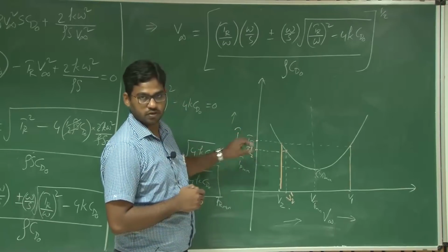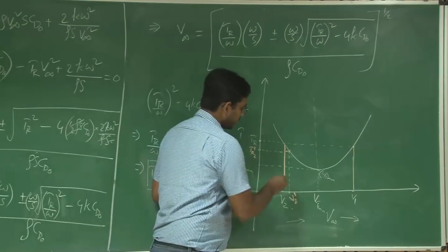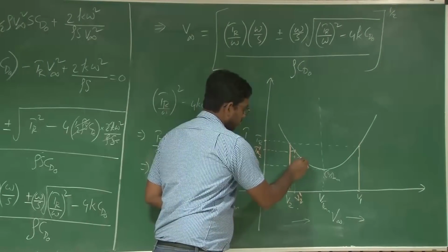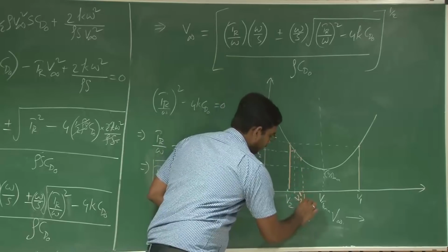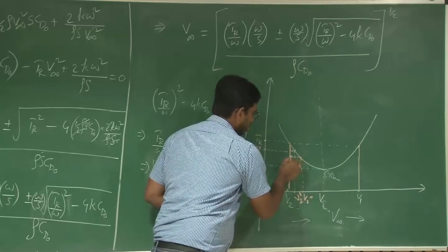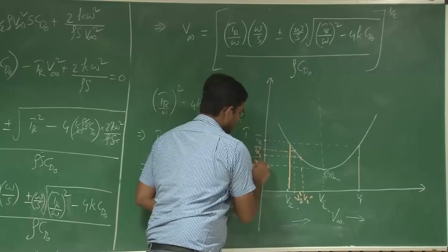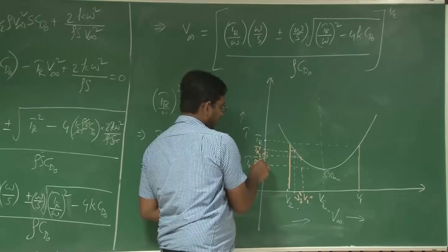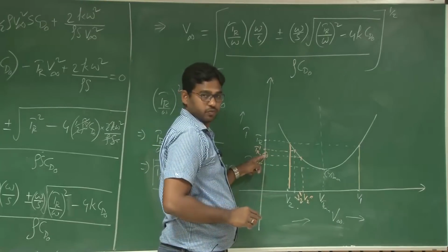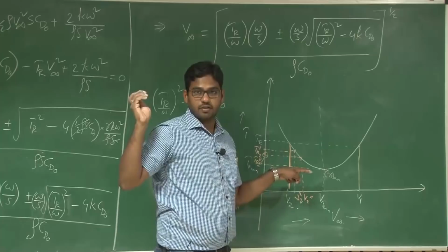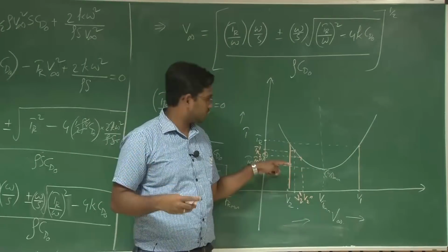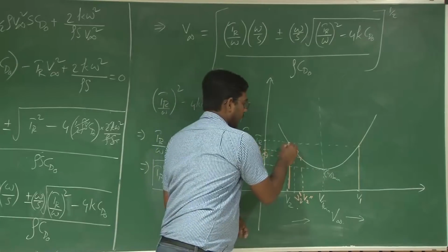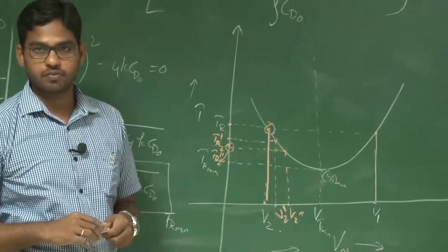So the vehicle tries to further accelerate, that means the velocity further increases, and say this to be v2 double prime, and the corresponding thrust requirement, this is your Tr2 double prime, has decreased further. So the drag of the system decreases, and this further accelerates. So you are not coming back to your initial equilibrium, right.